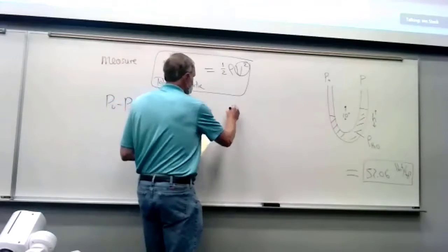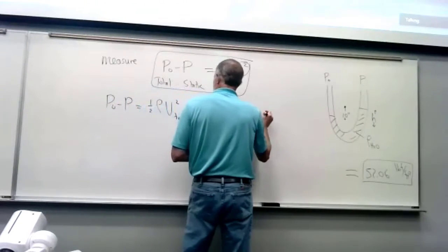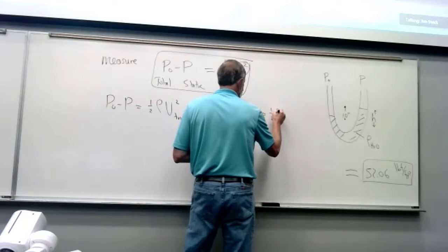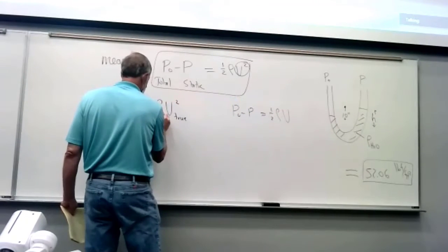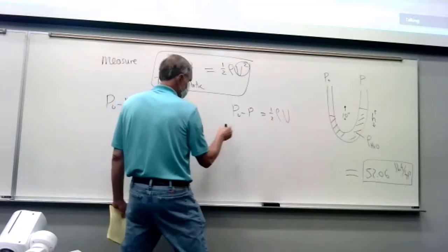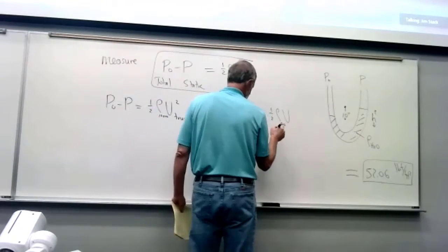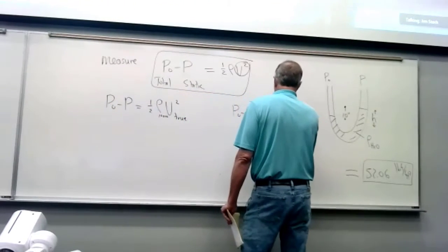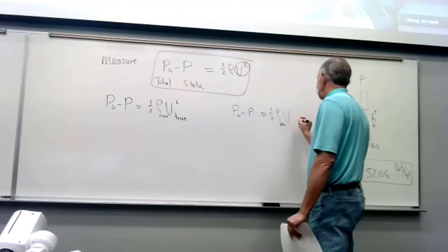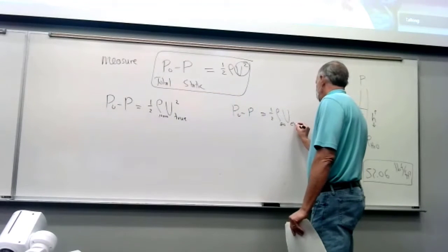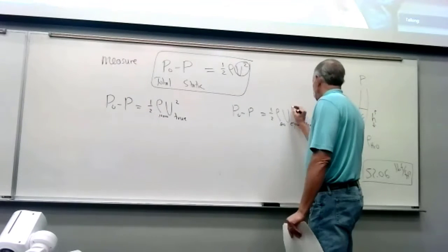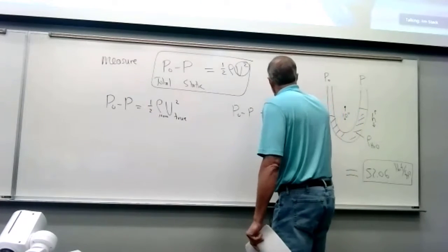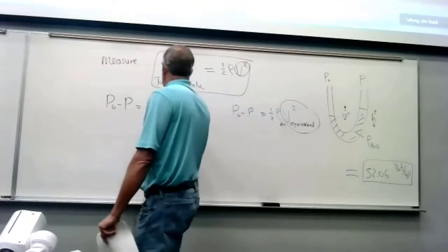And then the other way is assuming that our instrument on board the airplane, that's at 10,000 feet, this is at sea level, can't measure density, and so we just use sea level. So with this one, we get equivalent airspeed. This one, we get true airspeed.